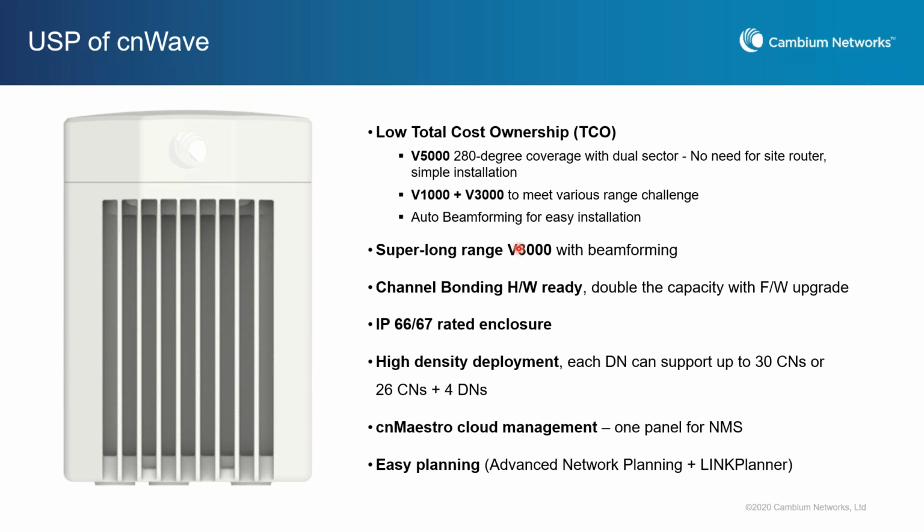We also thought about when we need multiple units to cover the area with mesh. With this 280 degree, we reach a pretty good balance between coverage and the nodes we need. For all the designs we have been engaged in, we only need a single radio per tower. So this really gives a significant cost saving.